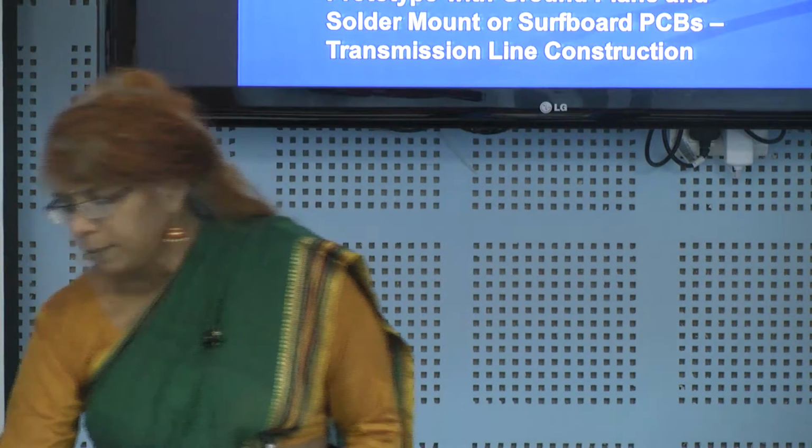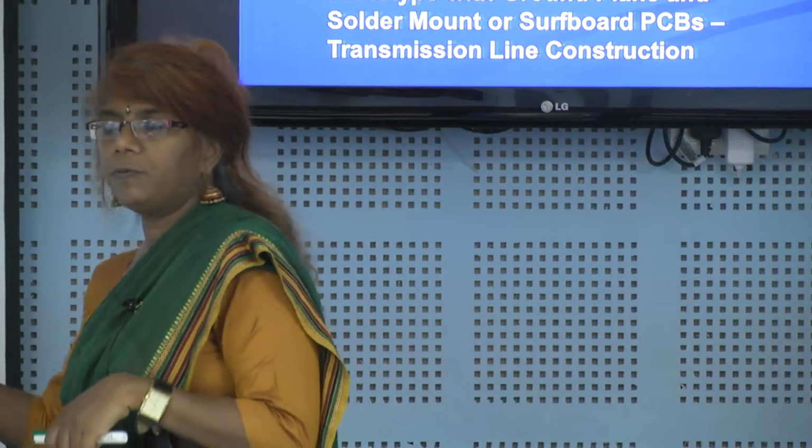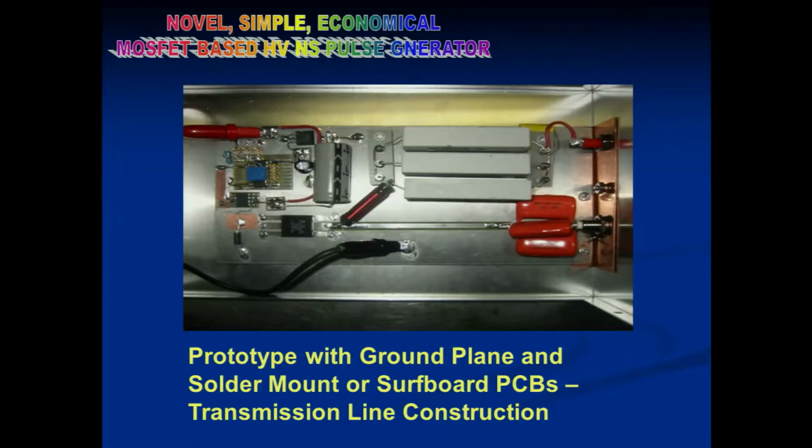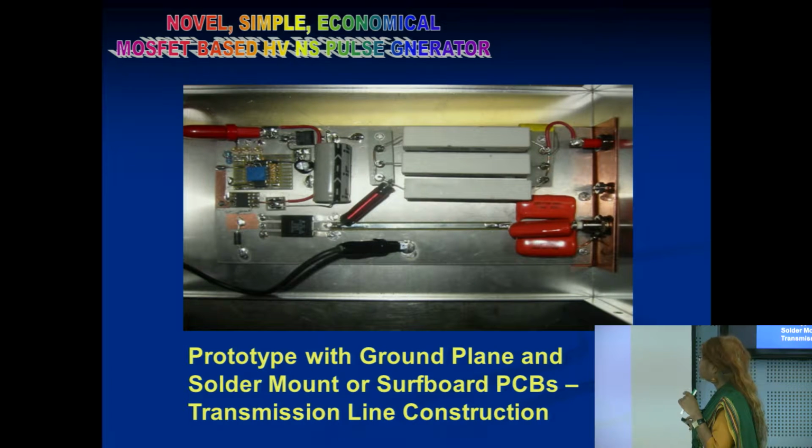This is the pulsar he built. We did lot of work, all my work is done from this one only. These are like military grade resistors, they will withstand very high heat. Ceramic. Sandeep, this is a ceramic resistor, we do not use it normally. In the lab you use carbon wound film resistor, but here you cannot use that. You use a high quality, everything should be the best quality.